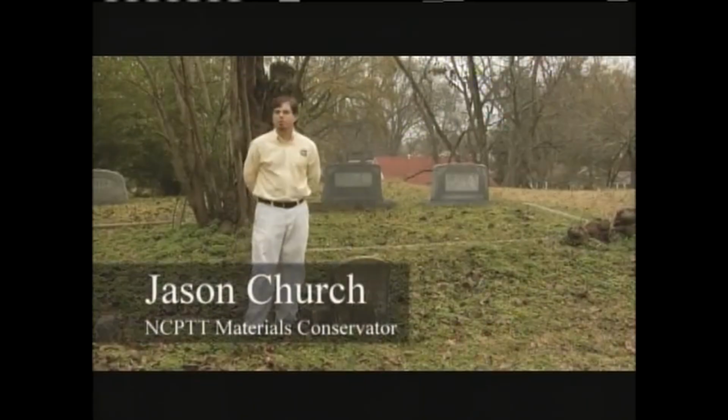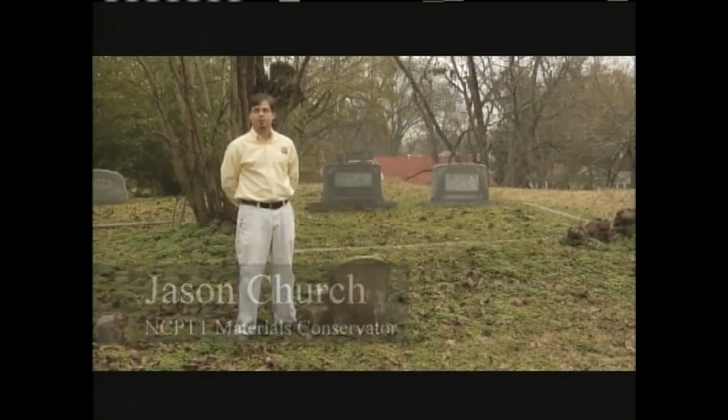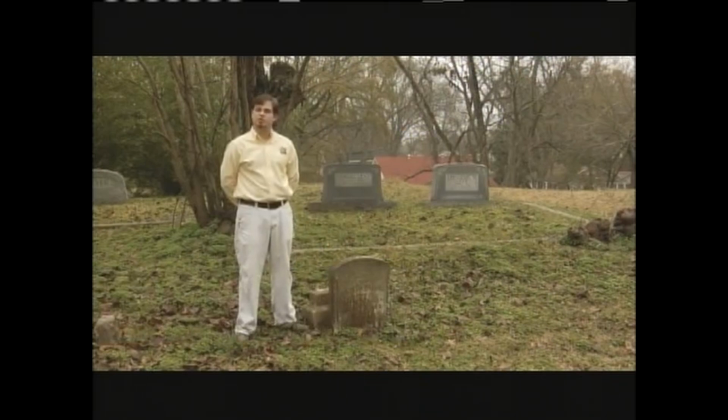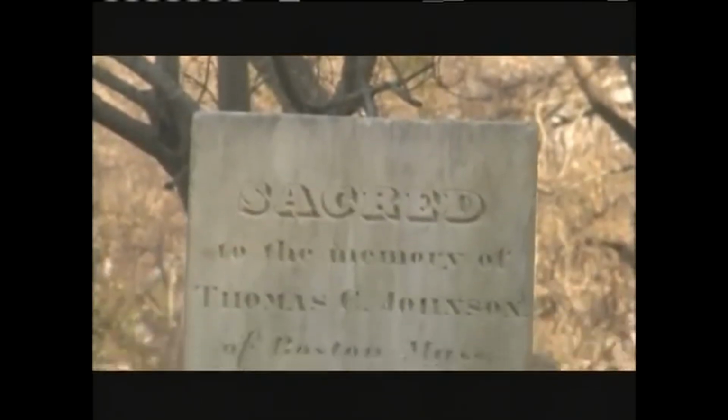Hello, in this video we'll be covering the basic procedures for resetting a stone grave marker. Now, two important things to remember when doing this is personal safety and also the object itself. We want to make sure to do no harm to the marker. Grave markers are extremely heavy, but also extremely delicate. These are pieces of historic fabric that have been weathered for a long period of time, so exercise caution before proceeding with any treatments.